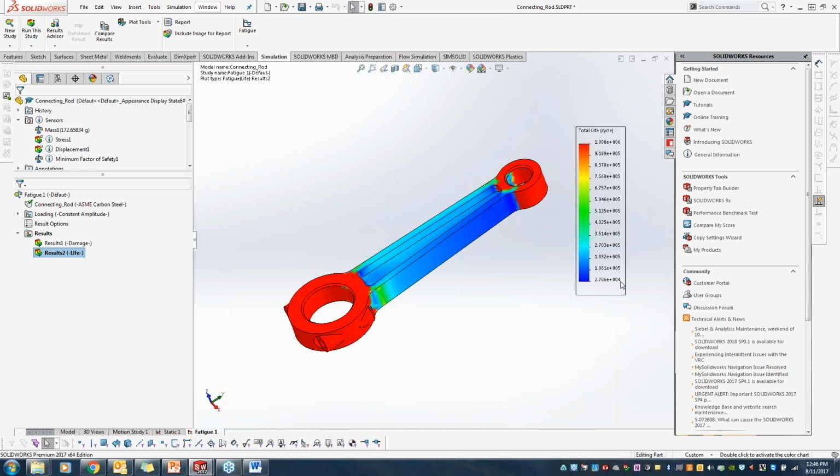It looks like what I've designed here, tested from the initial point to the last stage, is all ticking the correct box for me. Initially what I was thinking, how progressively I've modified to minimize the mass and have at least a 1.5 factor of safety, and even for, let's say, 2.7E4 cycles, it won't fail. Again, you have the option to get back, add more trend tracker studies, and make sure you're meeting the total life as you want, the best configuration as you need it.